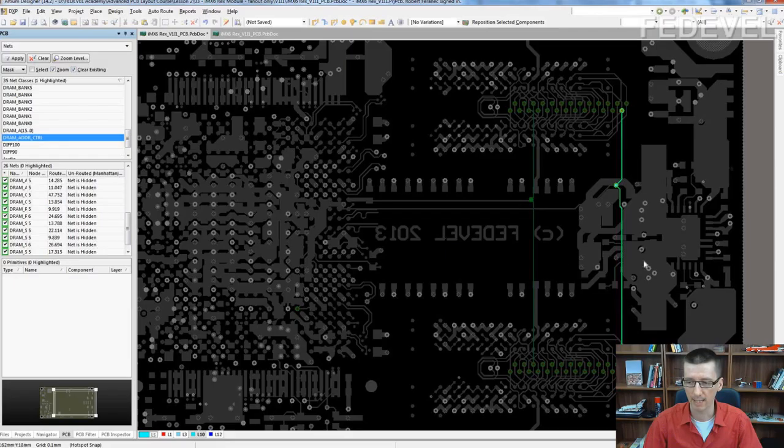And what can very easily happen, for example, in this particular case, let's say we have 26 nets, and you can very easily route 23 nets, but there may be a problem to connect the last 3 nets. There will not be a way to connect them. You will have to delete a lot of your work which you have done. That's the reason why I don't route full connections.